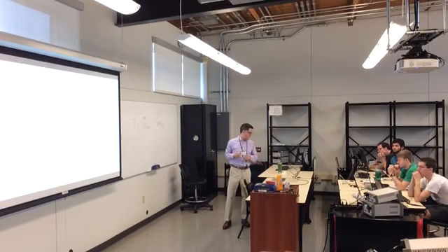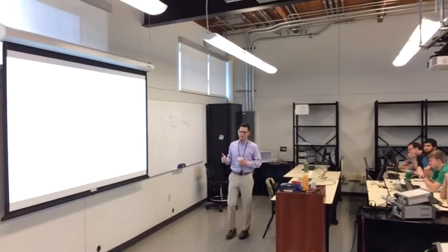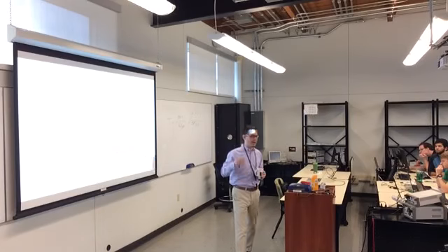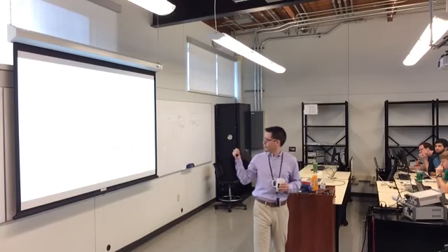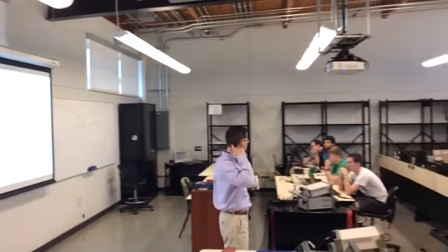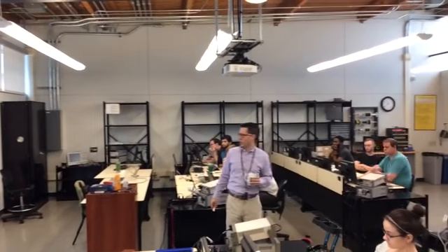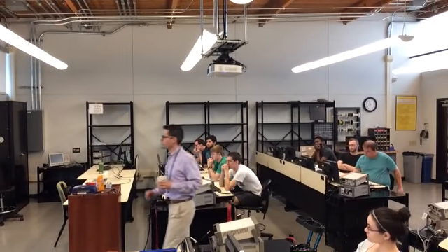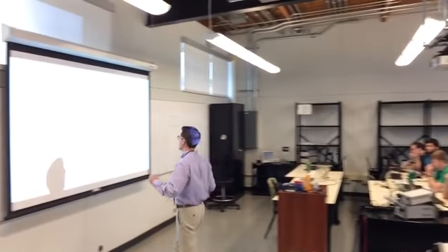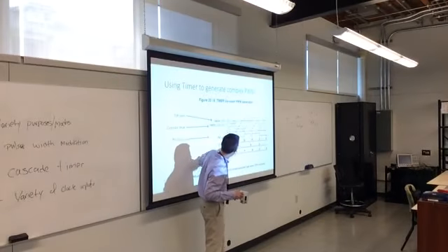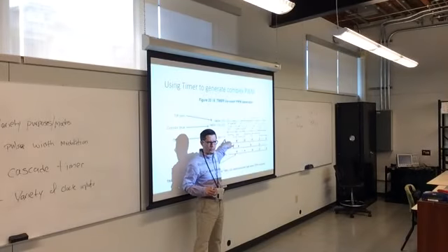We talked about up mode. We talked about down mode. They just count up, they just count down. This is the PWM count up mode, and I'm going to go over this quickly to explain it. The timer can control this output pin right here, this CCX pin.